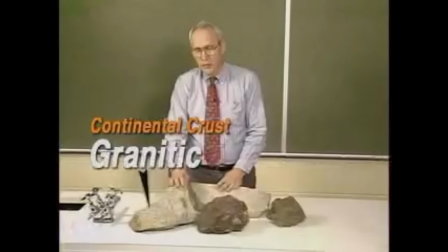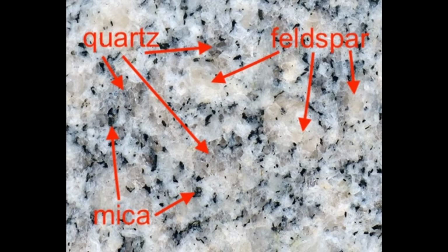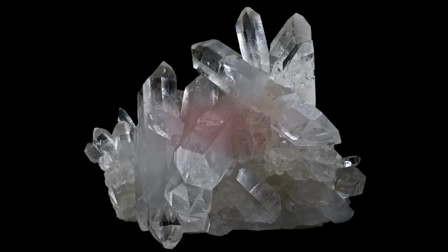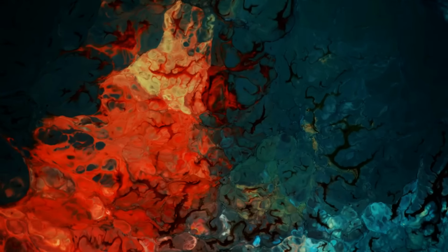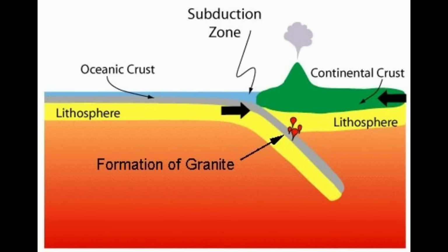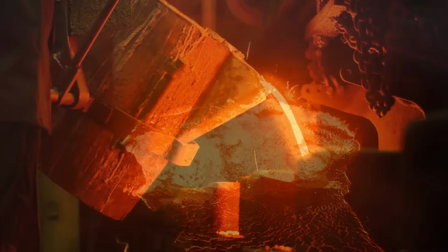Granite, on the other hand, also an igneous rock, is felsic, dominated by quartz and alkali feldspar. These minerals have different, much higher melting points. Quartz won't melt until 1700 degrees Celsius, for example, and they melt incongruently. Then, when the melt cools down, these different materials begin to crystallize at different temperatures with different rates, creating stresses you cannot remove unless you subject the stuff to very high pressures over long periods of time. The same high pressures over long periods of time that it took to form the granite in the first place. So, basalt's ability to be melted and cast easily makes it somewhat special among rocks.